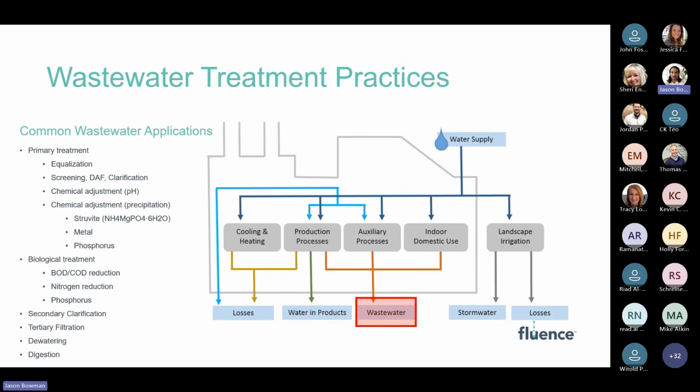As the potential for wastewater reuse comes into the equation, then we start to think about how all of these prior treatment steps might impact our ability to reuse water at the end of the process. So that could be the organics remaining in the wastewater, the nutrients remaining in the wastewater, the solids, etc. In almost all reuse cases, having a stable and reliable secondary wastewater treatment plant is critical, as this usually ensures the removal of contaminants that may otherwise impact the efficiency or efficacy of reusing treated wastewater effluent.